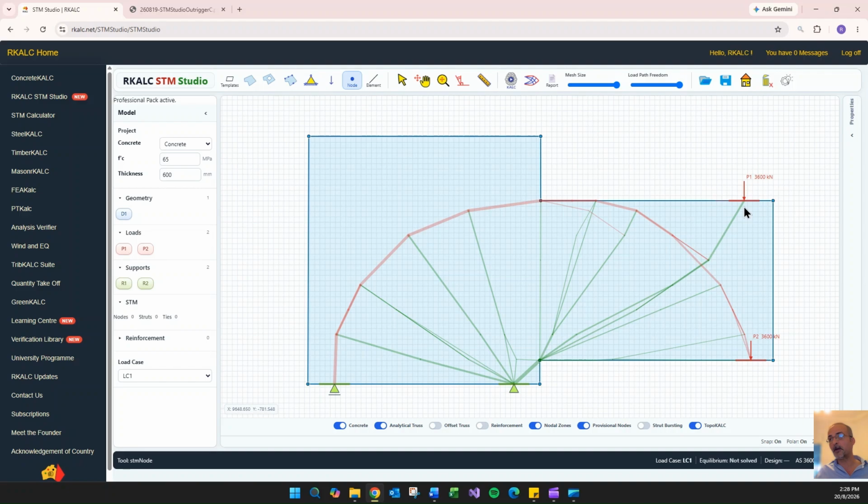So you just start by doing nodes, just throw nodes wherever you want to, and then pick up the supports with the nodes, put them inside of the domain, because the software will essentially start with the nodes only on the surface of the domain. Now you can bring them inside of the domain, and we need that actually because of the width of the struts and the ties. They should be fully included. And then click on element there.